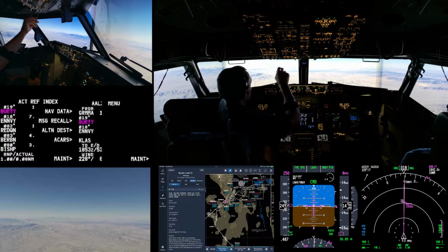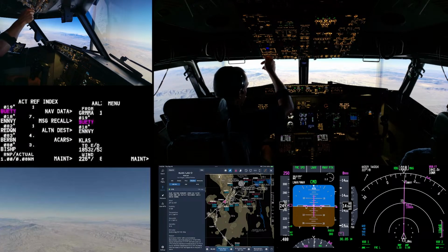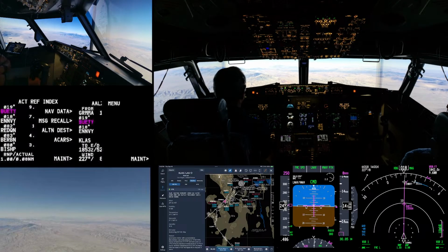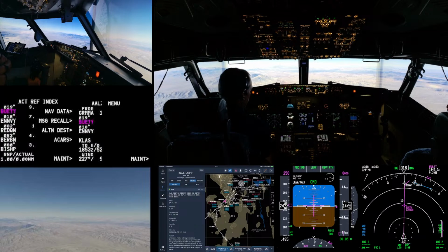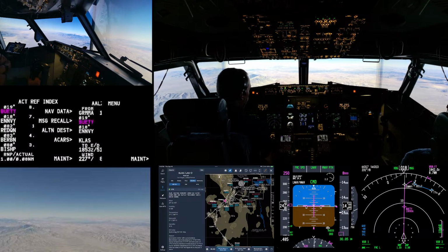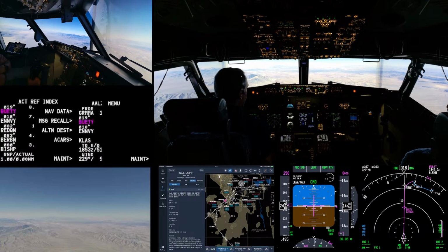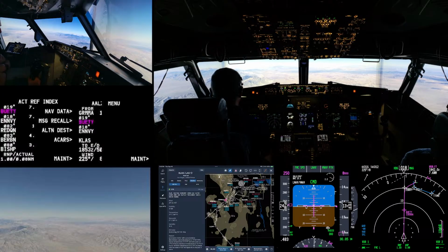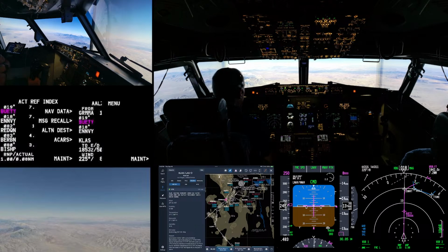Let's see, let's do a little fuel balancing here. Got 185 on the left tank, 201 on the right. So I shut off the fuel pumps on the port side and put the crossfeed valve in, so it'll start draining off of the starboard side. And of course, that's why I've got my fuel tag here. Now I am basically at idle, so it's not really going to draw too much, but it's coming down.